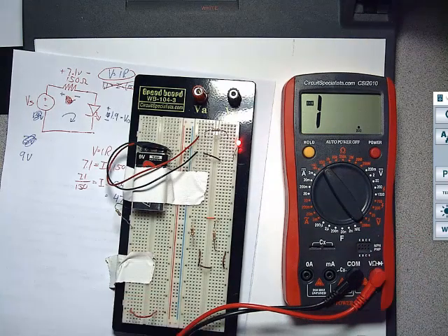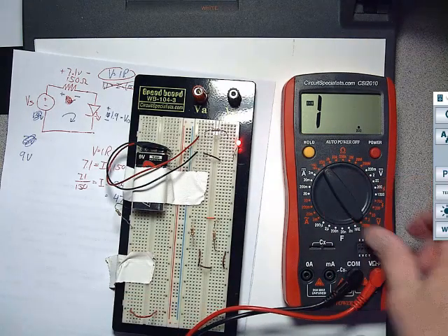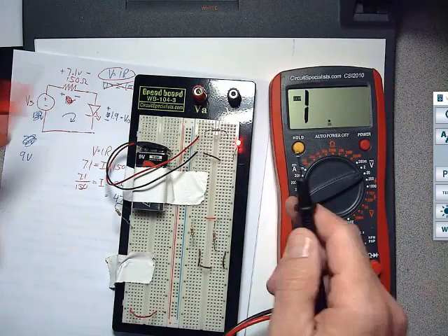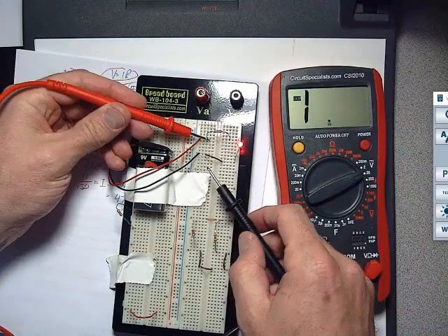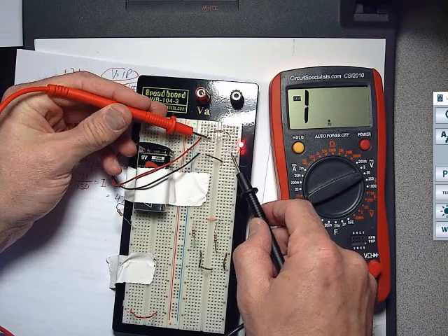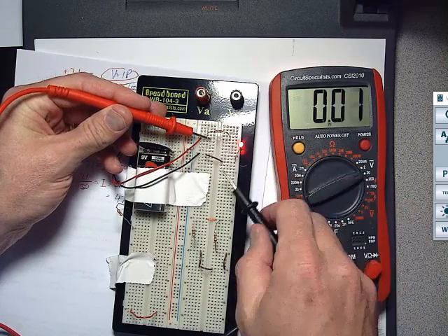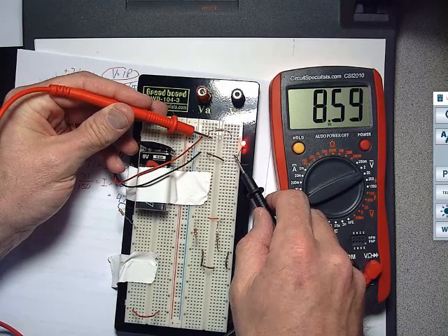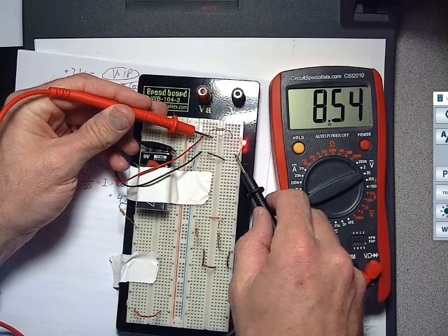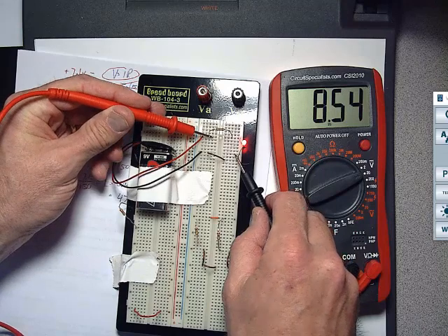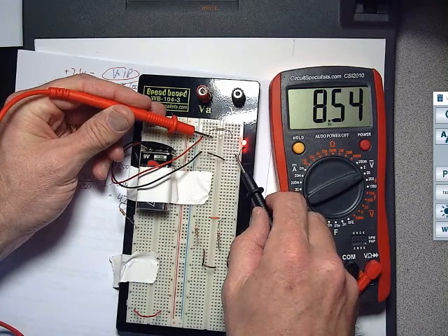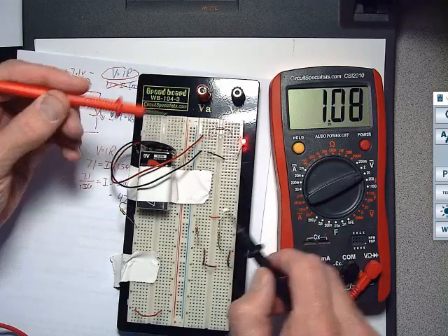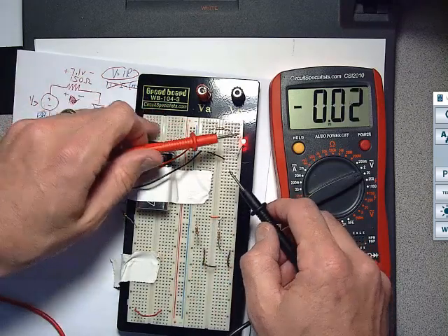Magic. All right. Now I'm curious about the following. I'm going to measure some voltages around this. First thing I'm going to do is measure the voltage coming out of my battery. So I'm going to go from this terminal to that terminal, and what do I got? This crappy 8.55 volt battery! I bought a 9! That's all right. We know that this is how it works. We do the calculations based on ideal values, but we have to measure and figure out what the actual values are. Now, I'm going to ask you, what do you think is across the diode?